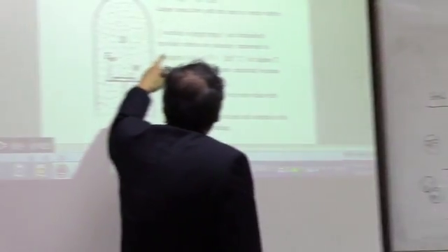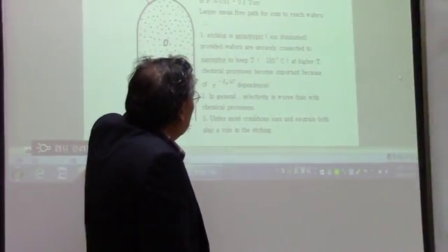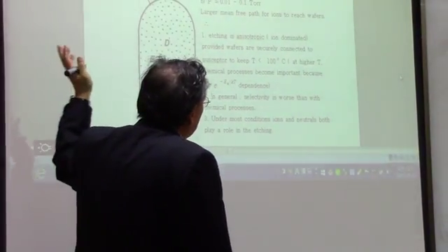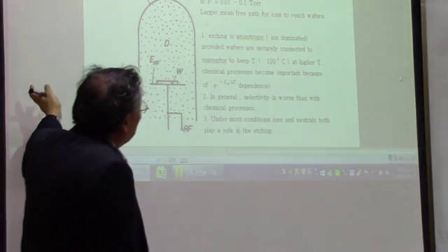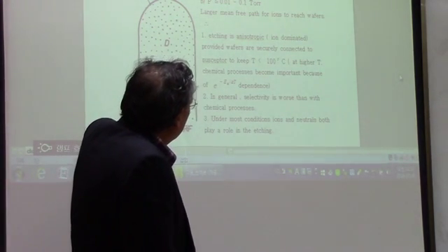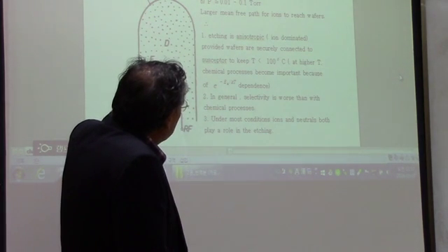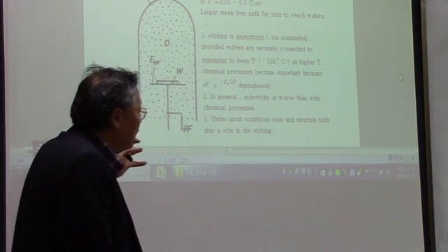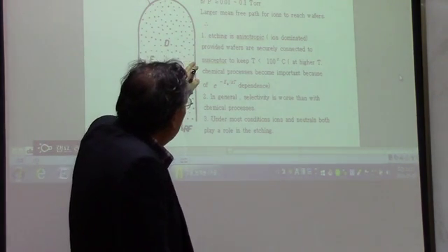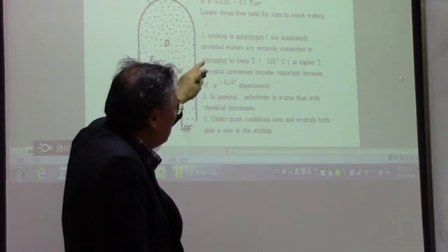And the pressure should be relatively low compared to the planar and the barrel type reactor, okay? Because the accelerated ions have to have a large mean free path.